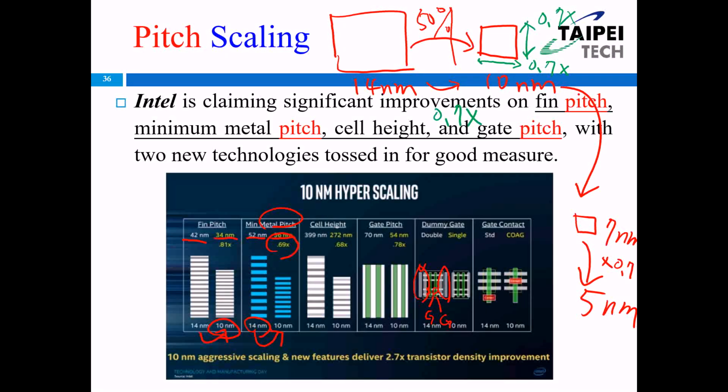We deposit the metal line on this white area on purpose in order to protect the inner transistor. Okay, so for this white metal line, the white gate region, we call it dummy gate. Or you will hear dummy gate very often. Okay, so next time when you see dummy, you need to know it's not real. It's fake.